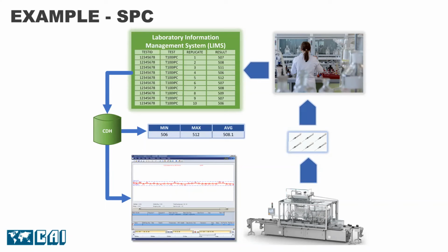With the SPC chart, we could make a rules-based control strategy. For example, if the weight was trending upward for 2 sample sets by 2 sigma, the operator would turn the control knob one click counterclockwise.